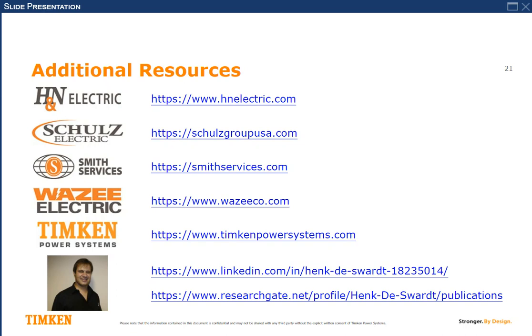Yeah, that's a good question. I've had this question before from customers. If we look back at our losses, there are different things that we have. We have a frame of the machine that lasts 100 years, the mechanical frame. We have the core. As long as we test the core before and after each rewind, we can qualify the condition of the core. We can qualify if the lamination material is degrading by looking at the losses. And like I've shown in the presentation, we can see when the losses are too much and would influence the repair or the machine performance.